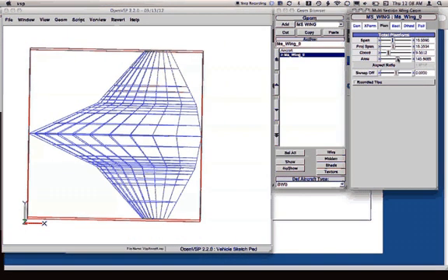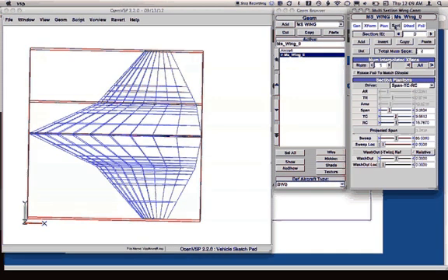And again, notice when I change one slider, some of the other sliders change as well. That is because the area is a function of the span and the chord. So when you change one, you automatically change the other. Now when you go to the section properties, you'll notice here that there are various sections, and you come over here and look at the various section IDs. Notice how they become highlighted as part of this.